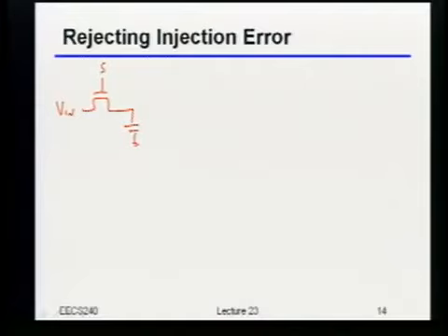So what we're saying is happening with this charge injection is that the output is, of course, going to be my input, but it's also going to have some offset in it, just because when the switch turns off, there's some fixed amount of charge that's going to jump into the output. Plus, we're going to have some residual amount of error that's dependent upon the input voltage. Okay? Let's ignore that residual error that depends on the input voltage for now.